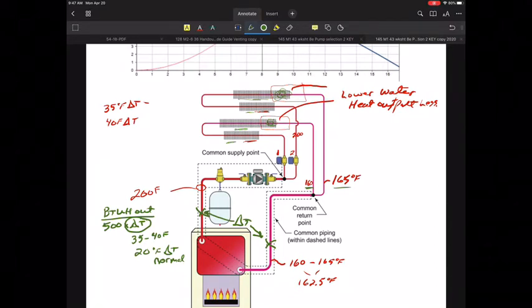In most cases, you're going to get a benefit by having more water flow simply because it lowers the delta T between the supply and return, and it offers more heat emitter output out of the runs on the end, out of these last baseboard, whether it's here or here. Those emitters are going to get more output because they're going to see a higher temperature going into those baseboard, and that will give them more BTU. So that's really why we would want to do that. The delta T is really the key that we are looking at, and that's what you have to decide. Design delta T's can vary a lot, but that's another lesson that we'd go through.